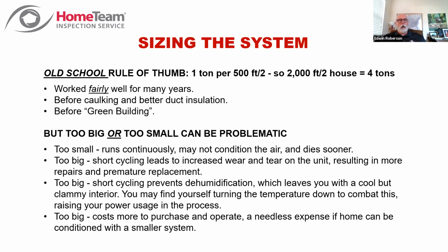Too small, it's just going to run more continuously. It may not condition the air. It's just always lagging behind. It just can't catch up with the space it's in. It's not going to last as long because it's running all the time. Too big, you're going to be short cycling, more wear and tear, and more repairs.